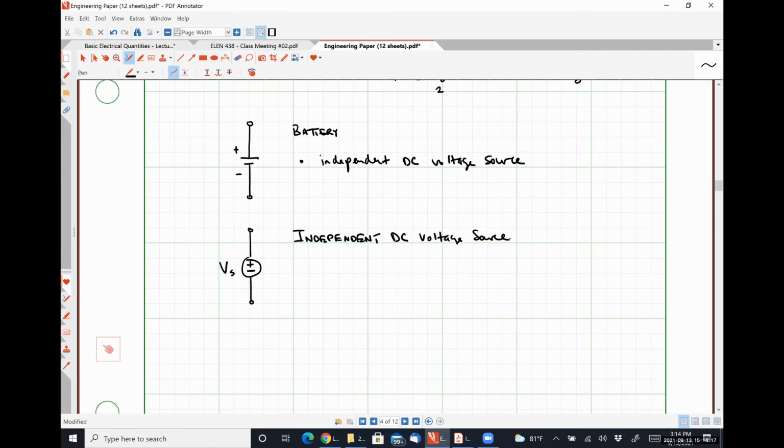What we'll find, and again, we'll talk about this in lecture 9 of this class, I believe, is that we can correct these ideal voltage sources to behave more like a practical or realistic voltage source by simply putting them in series with a resistor, where that resistor limits the amount of current that can flow, okay?